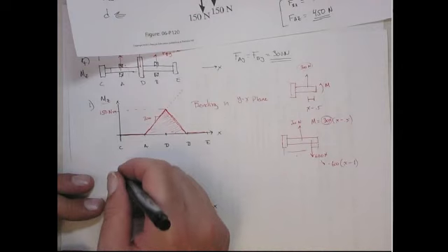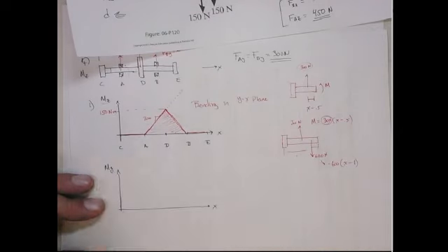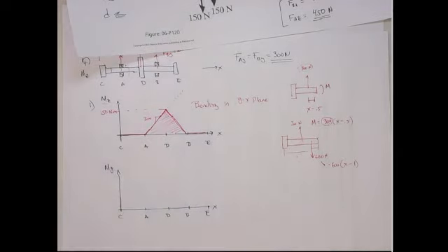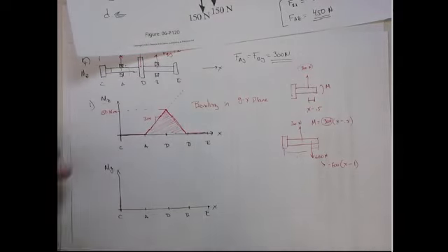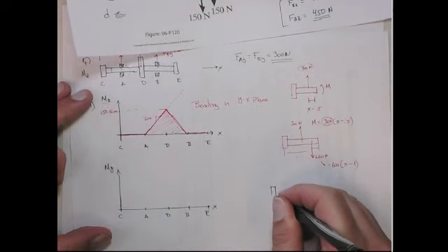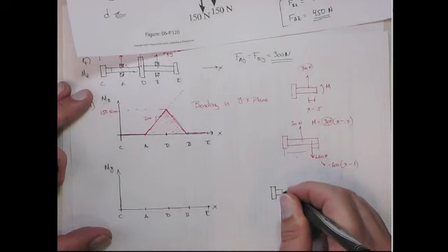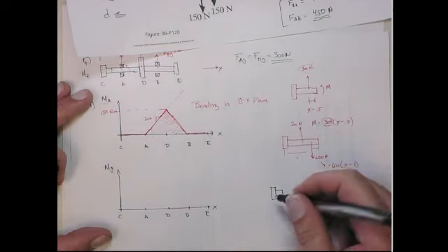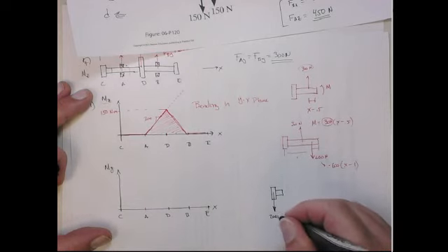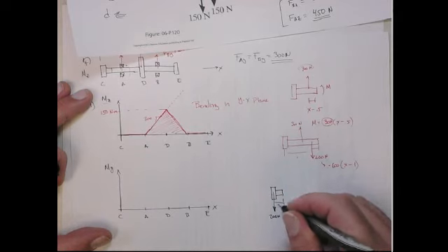All right, let's look now at the other plane. Here's x. Now we're looking at the bending moment around y. We're at the same points: C, A, D, B, and E. Okay? But now the forces look a little different. So between C and A, the only thing we have is downward 200 newtons. This distance here is going to be x.